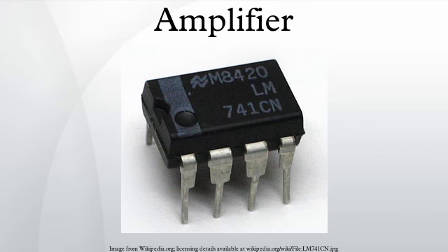Musical instrument amplifiers. An audio power amplifier is usually used to amplify signals such as music or speech. Several factors are especially important in the selection of musical instrument amplifiers and other audio amplifiers. Frequency response: not just the frequency range, but the requirement that the signal level varies so little across the audible frequency range that the human ear notices no variation. A typical specification for audio amplifiers may be 20 Hz to 20 kHz ±0.5 dB.